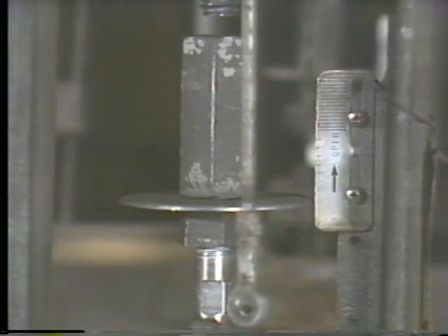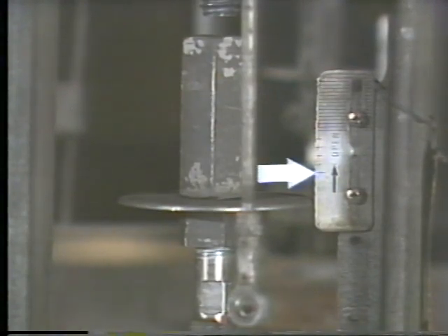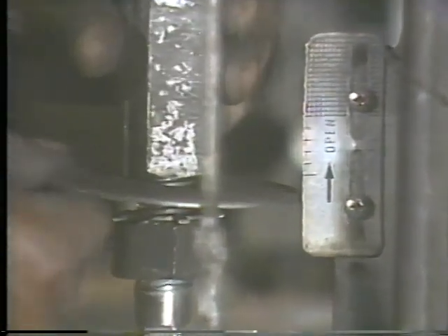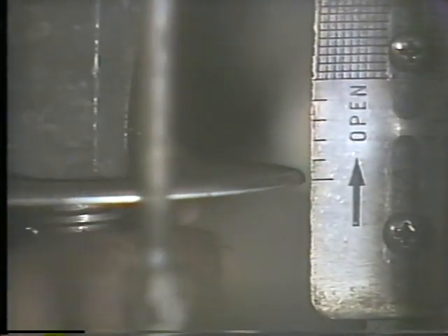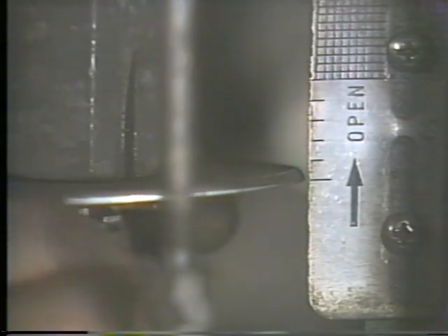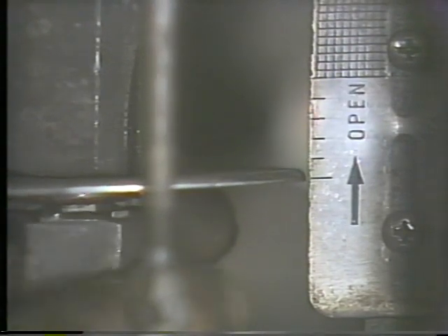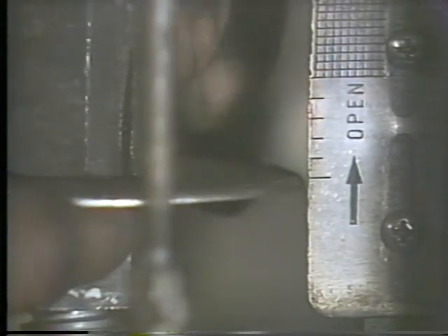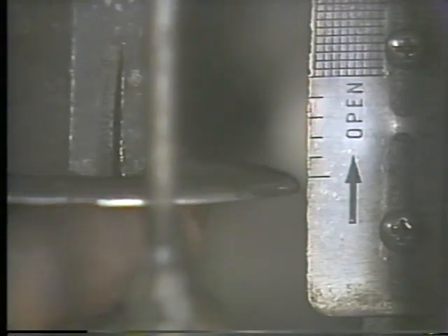What we want to do now is raise the travel indicator plate so that it is lined up with the lowest marking on the indicator scale. To do this, raise the long hex nut and the travel indicator plate. Then, raise the small hex nut until it supports the travel indicator plate at the low scale marking. Since the valve is seated at its lowest position, if the travel indicator plate on the valve stem is set across from the low scale mark, then whenever the valve is closed, the travel indicator will read 0 or closed.